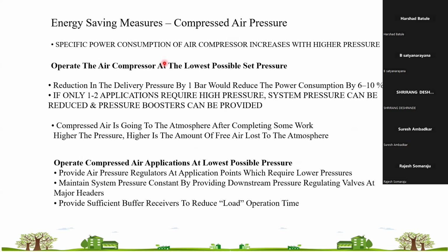Then there should be a good intake. During our equipment list, we see the air filter. The purpose of the air filter is not to pass dust to the compressor, but we see many air compressor filters that are choked and not regularly maintained.